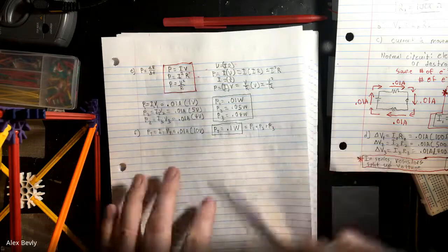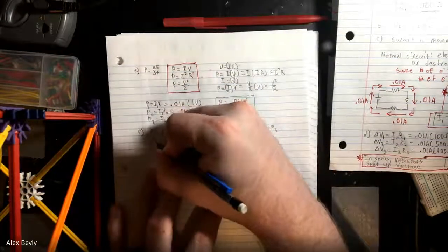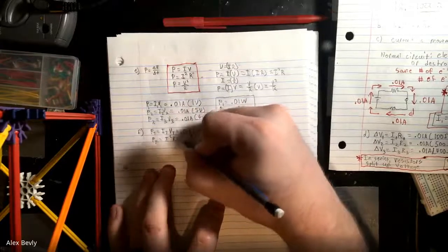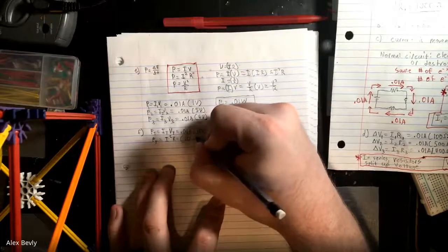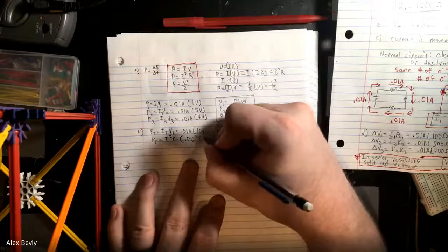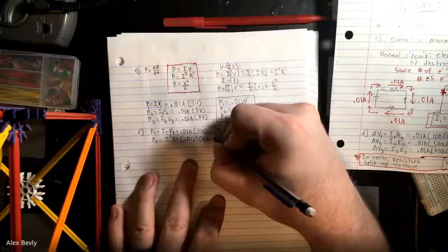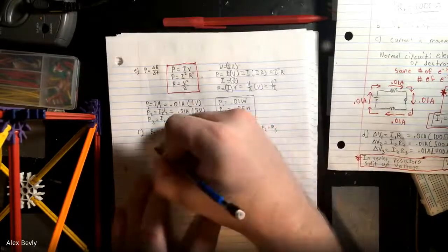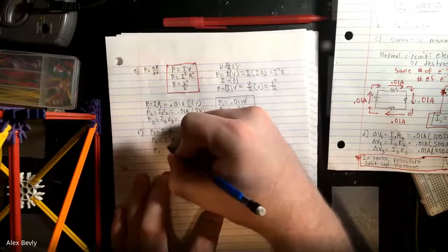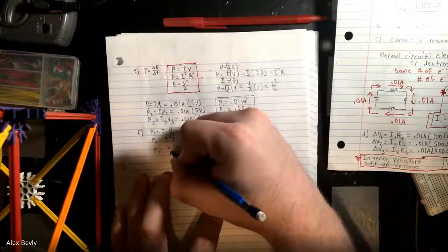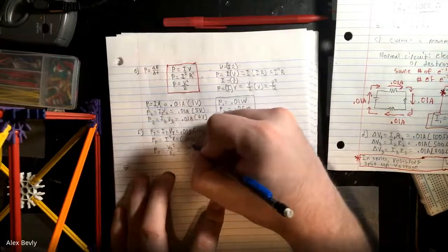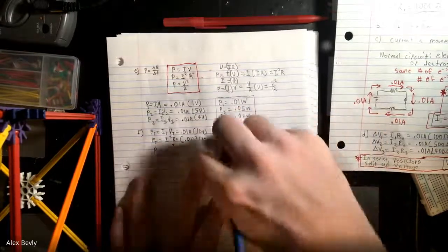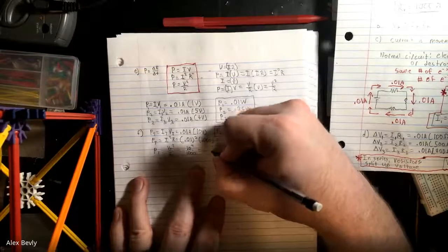And we can even test these other equations. That total power would be current squared times resistance. So my current squared is 0.01 squared times the total resistance of 1,000 ohms. We'll still get 0.1 watts. And we can do power total, which would be total voltage squared divided by total resistance. So 10 squared divided by 1,000. And you'll also get 100 divided by 1,000 is 0.1 watts.